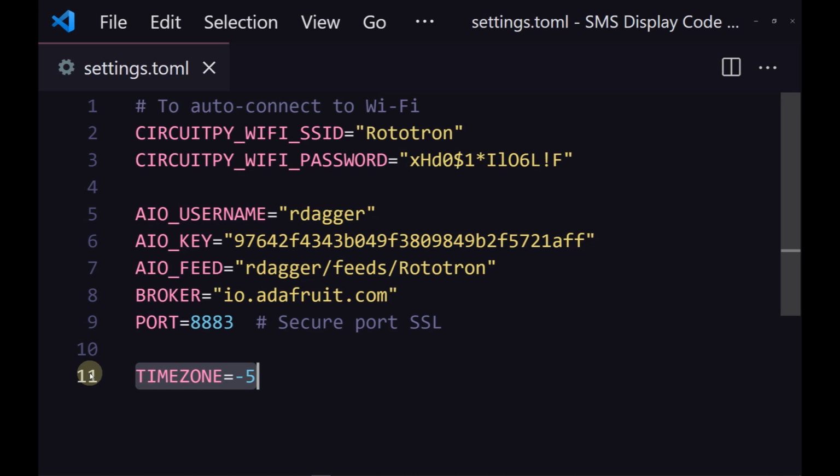CircuitPython 8 introduced support for environment variables. Environment variables are commonly used to store secrets such as passwords and API keys. This method does not make them secure, it only separates them from the code, so be careful not to post them to a public website such as GitHub.